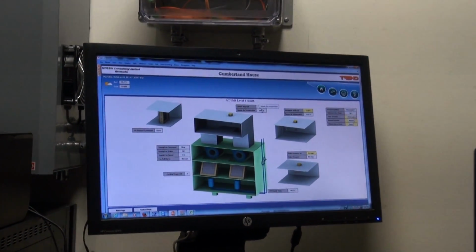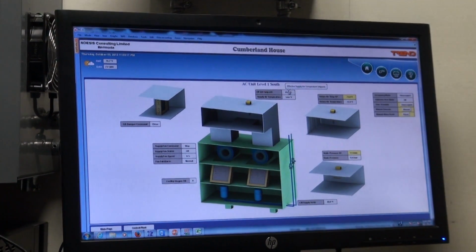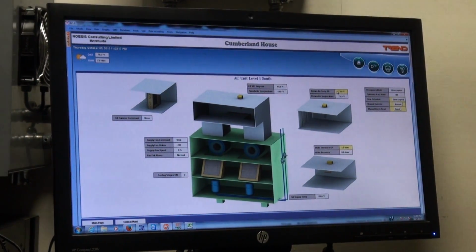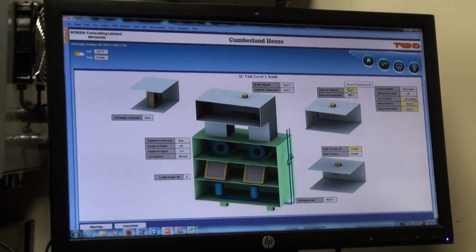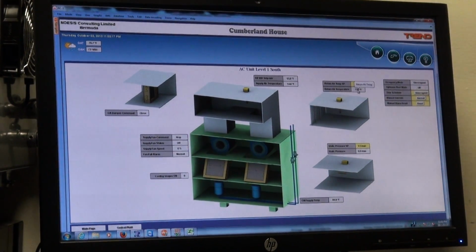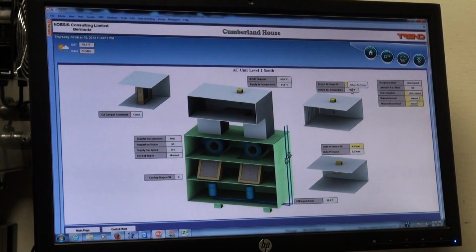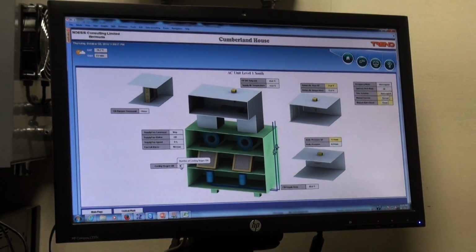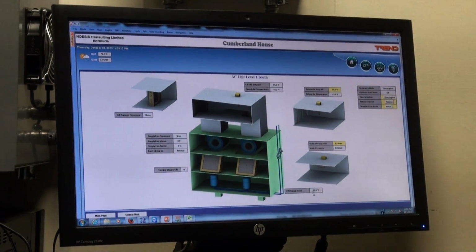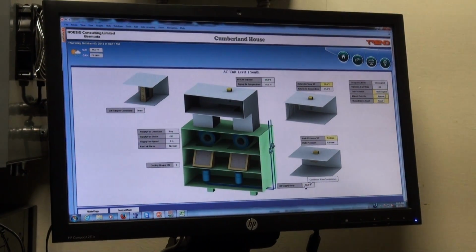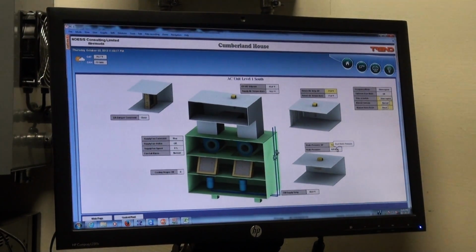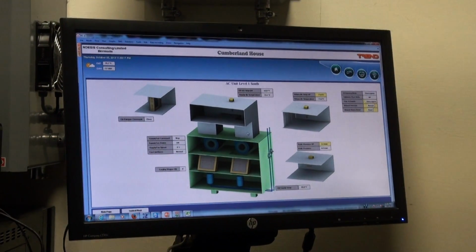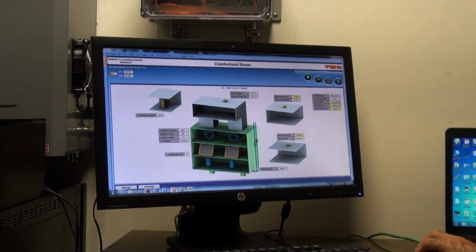We're measuring supply air temperature. We've got a set point. We're measuring return air temperature. That's the actual. We've got a variable return air temperature that we can reset. We've got an actual return air temperature. We've got supply fan speed, cooling stages. These are the temperatures that are coming out of the heat exchangers, as we just showed you. We've got static pressure, meaning if any of the VAV boxes are closed, this unit will not run and blow the ducts. That's a protection in the control loop.